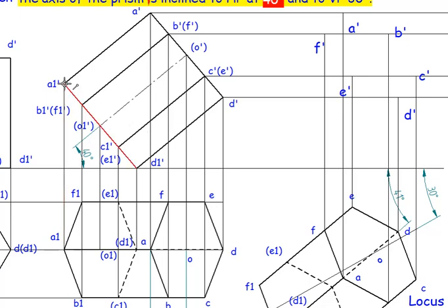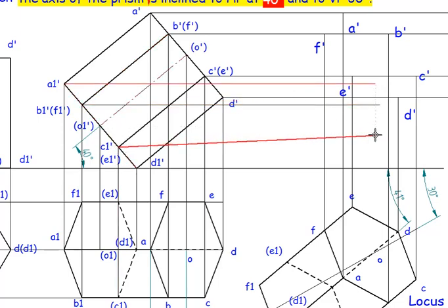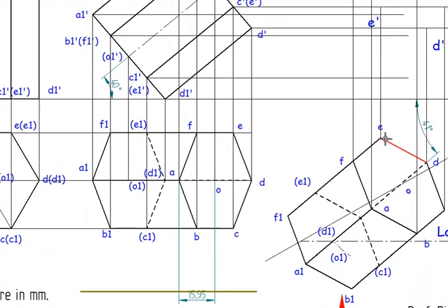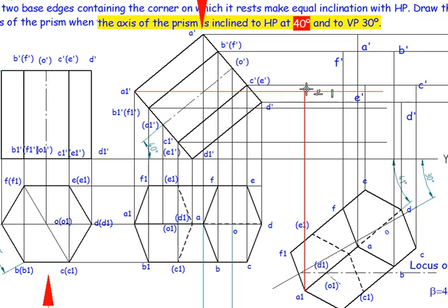So from here, A1, I'm going to project it, then B1, C1. So this is A1 projected to B till this point. That's why we are giving the end point there itself and give the annotations to avoid the confusion. Next thing is B1. B1 is still here. I'm going to be projecting it.